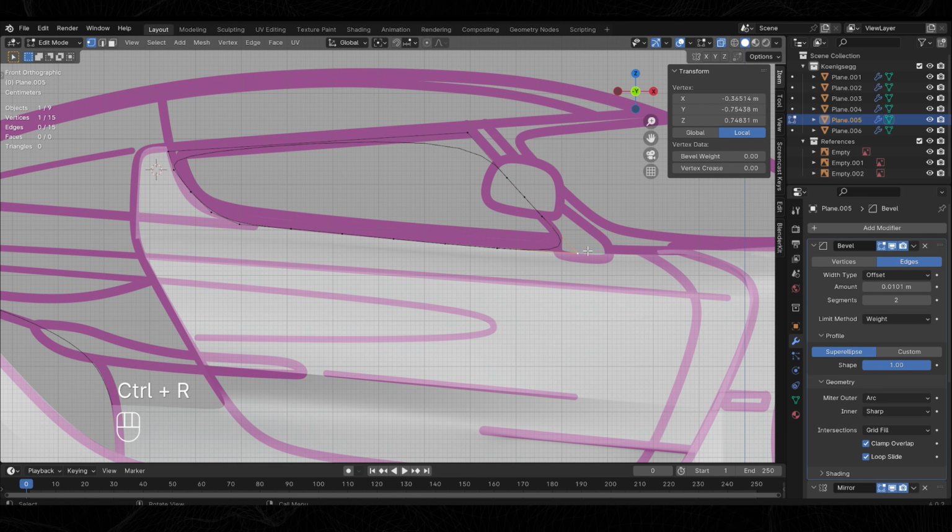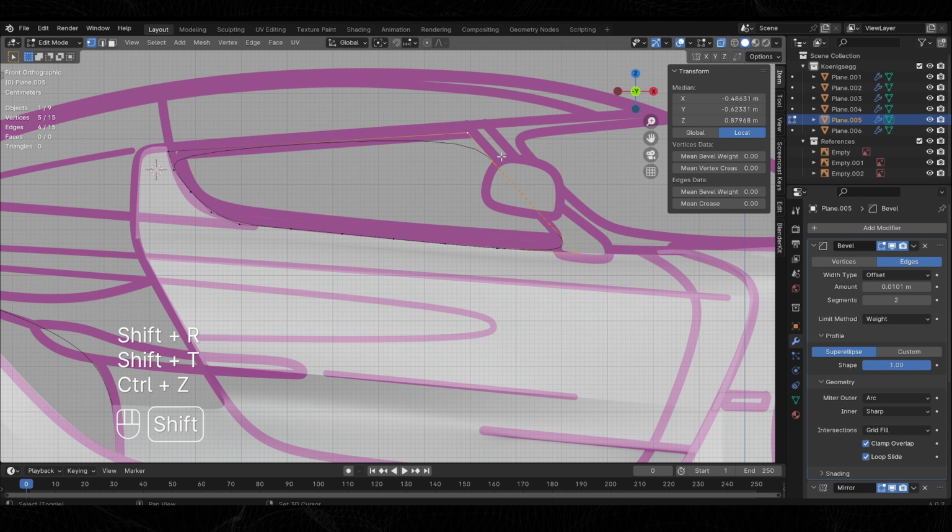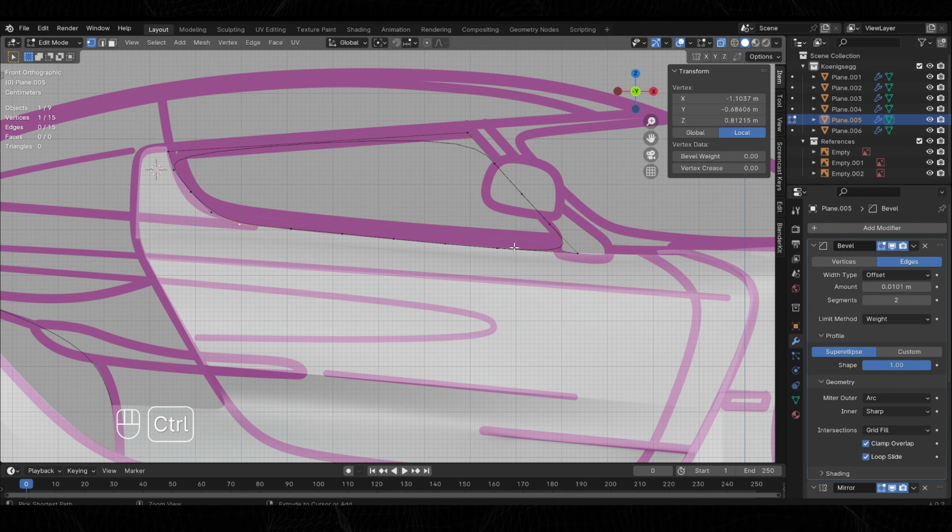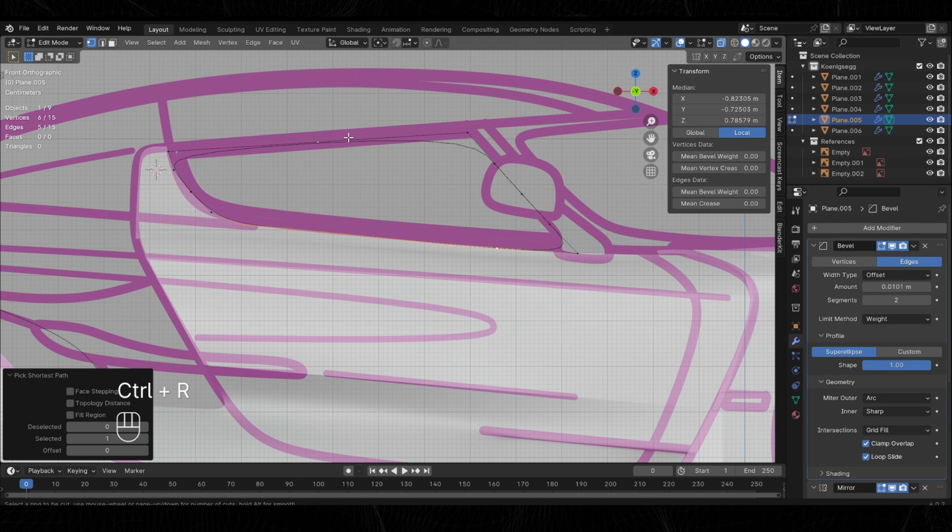You'll have to make sure there are the same number of vertices on the opposite sides of the window. So 5 vertices for the vertical sides and 7 vertices for the horizontal ones.